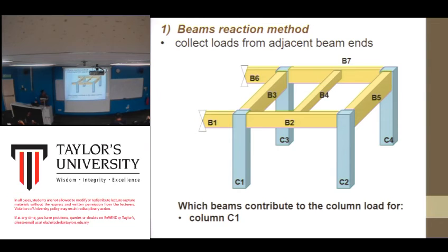You need to know how much load it transferred to this beam, then only you would know the reaction force for this beam. So you need to know these three. But this is only one level. You have ground level, first floor level, and the roof level, at least these three different levels. So just imagine how much time you need to analyze the column, to know the load on the column using this method. That's why we don't encourage you to do that. We don't want you to kill yourself with too much calculation.